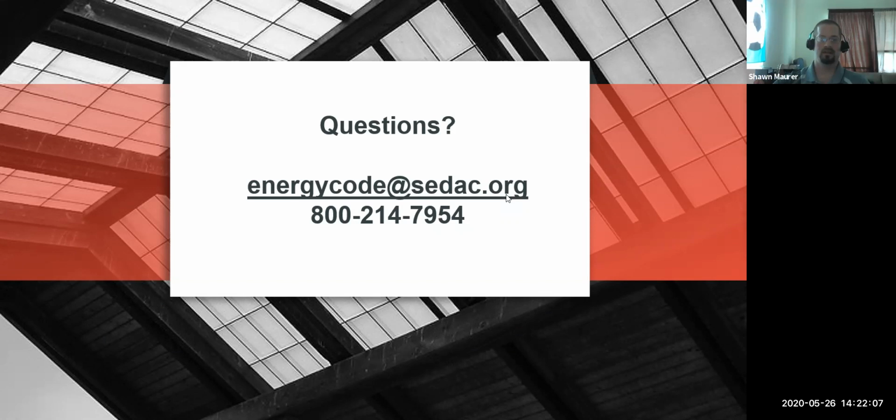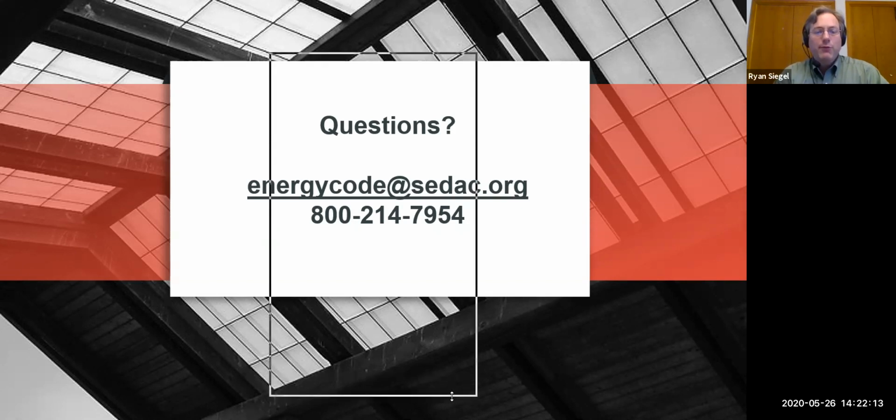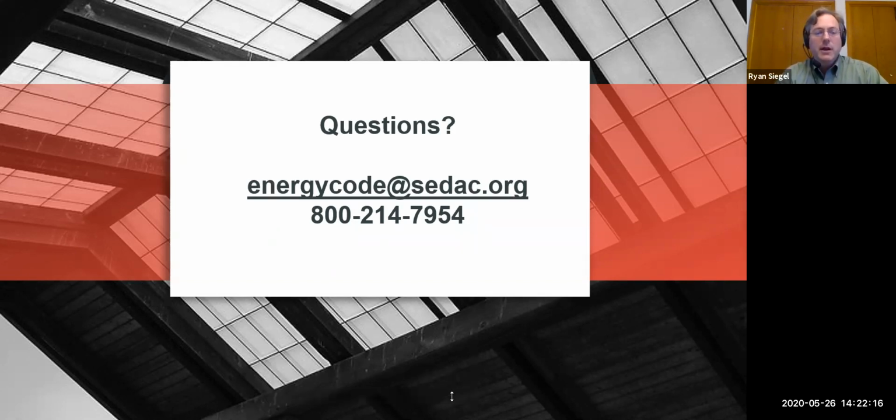All right, we're going to end our lighting poll here, share our results. Required for exterior lighting controls, time switch or occupant sensing, yes, and daylight controls, yes. Most people picked up on that both of those are required. Similarly, for which systems have to do functional performance testing, all of the above. Most people got a fairly good response on that. You have to functionally test all three of those, and lighting controls, you have to have time switch and daylight harvesting.